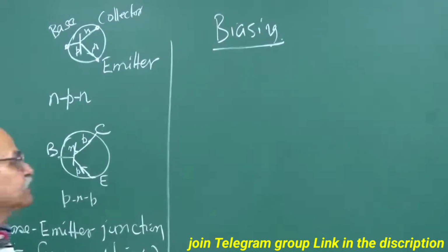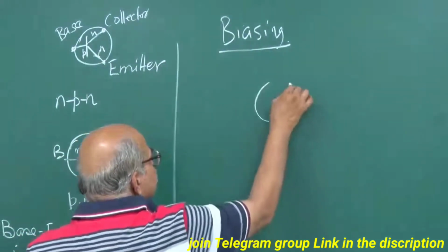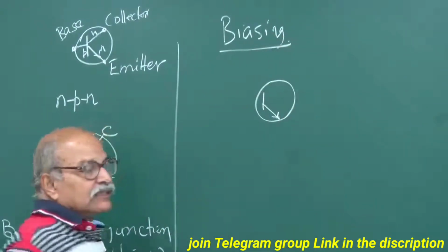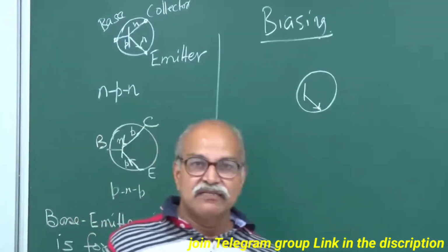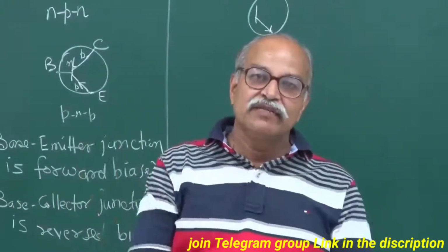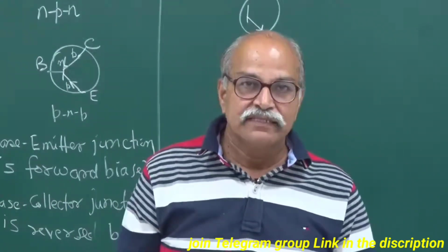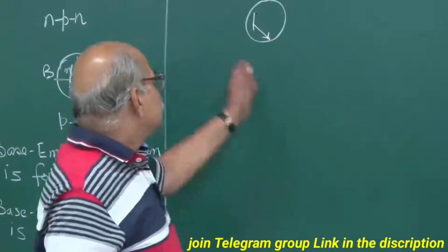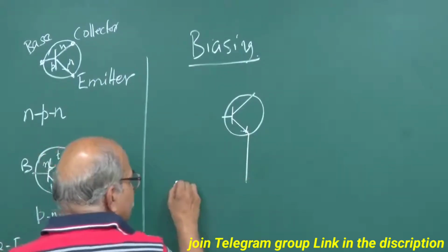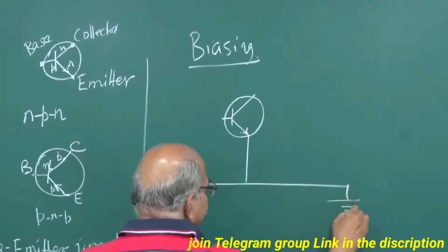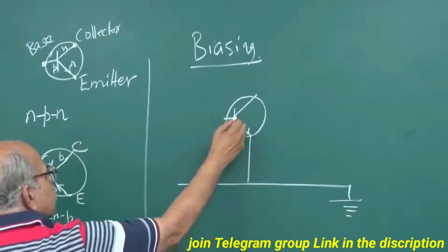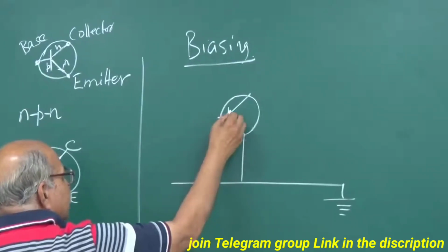One possibility is that you take this transistor, and this is the emitter side. I am talking in terms of NPN, but the same discussion, same description will be valid for PNP also. As I said earlier, all the arrows will be inverted and all the polarities of the battery cells will be inverted. So, if you have this transistor, then let us take this as the common terminal, 0 grounding, and then this base emitter junction should be forward biased, and remember this is NPN.